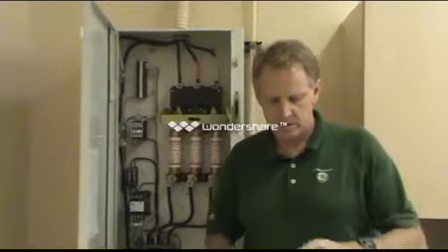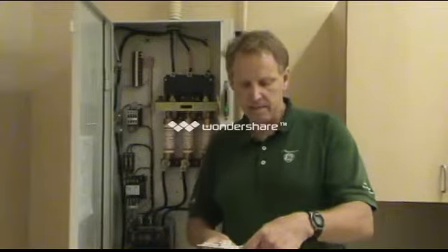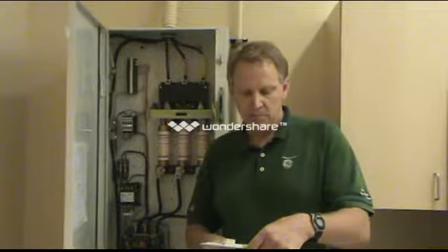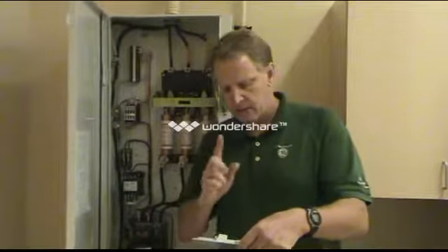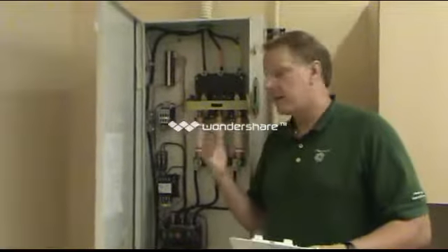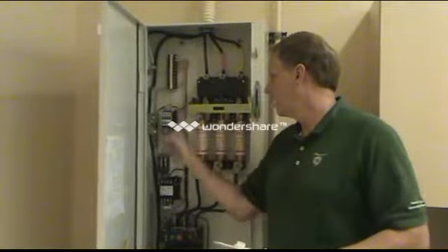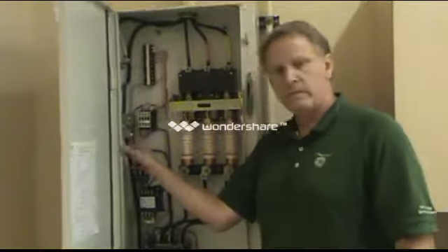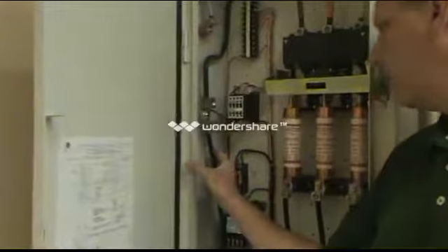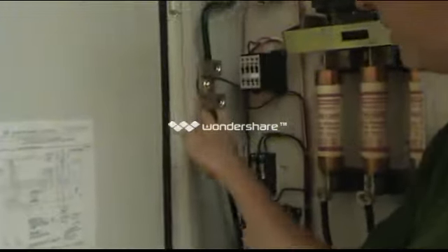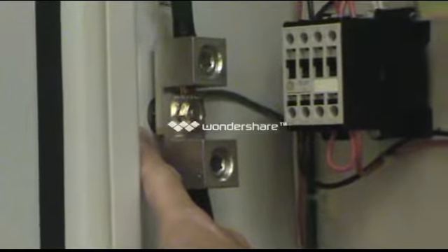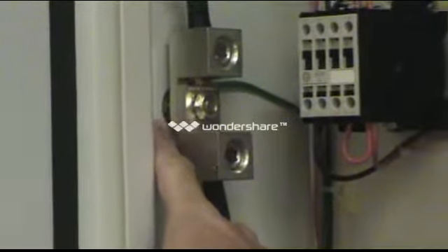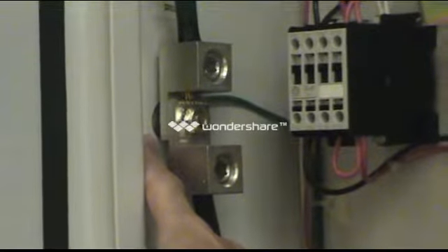All right, now we're going to talk about steps 8 through 17. Question 8. Are the facility and load grounds bonded to the panel, to each other, and to a non-painted conductive surface? Very important, because like I said before, we're going to have 2 ground paths going back to the source. In this example right here, they're bonded together to the panel through that nut right there, and to a non-painted conductive surface. This is a good example of how a ground should look.